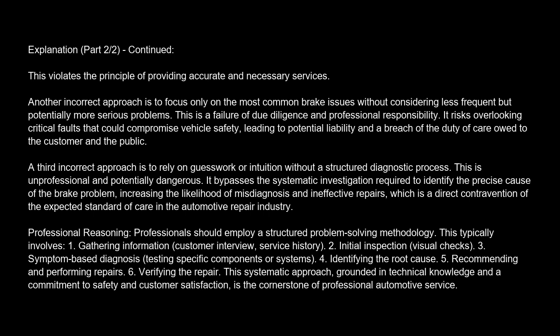Professional reasoning. Professionals should employ a structured problem-solving methodology. This typically involves: 1. Gathering information, customer interview, service history. 2. Initial inspection, visual checks. 3. Symptom-based diagnosis, testing specific components or systems. 4. Identifying the root cause. 5. Recommending and performing repairs. 6. Verifying the repair. This systematic approach, grounded in technical knowledge and a commitment to safety and customer satisfaction, is the cornerstone of professional automotive service.